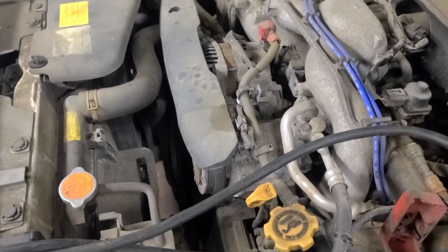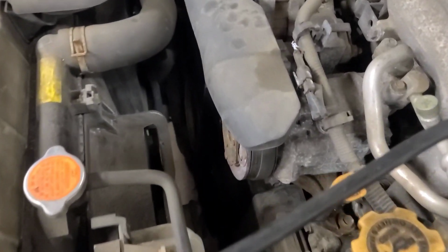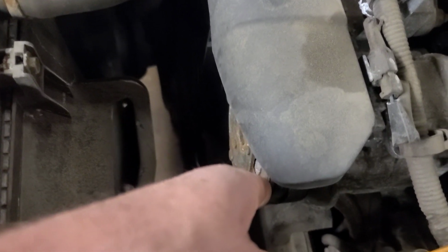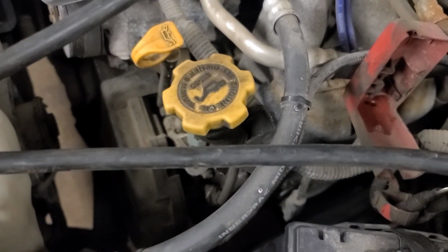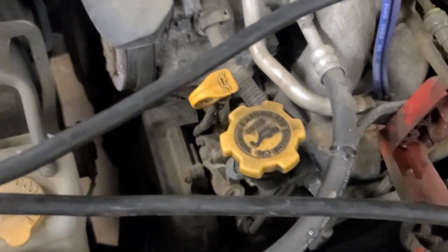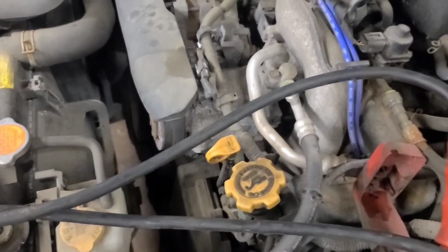So I've got the battery charger on it, set at 13.6 volts. And you can hear the radiator cooling fan cycling on and the AC compressor engaging. Sure, the AC compressor is controlled by the ECM, so why would it be doing that? And that's at the same frequency as the check engine light. Now the interesting thing is the check engine light is not flashing now. It's on steady.